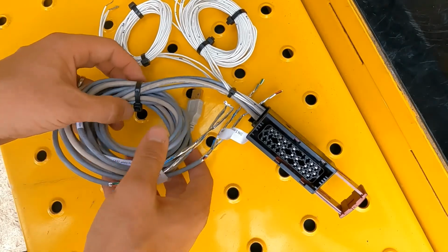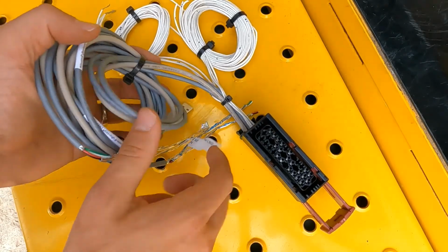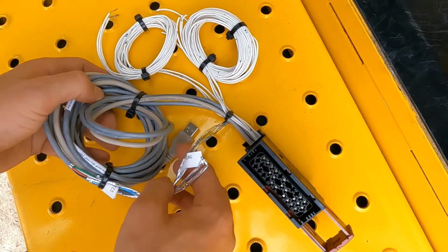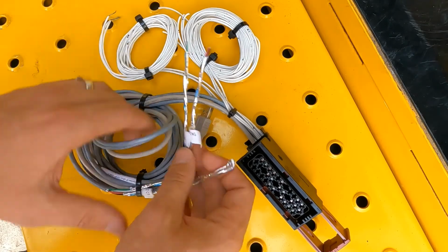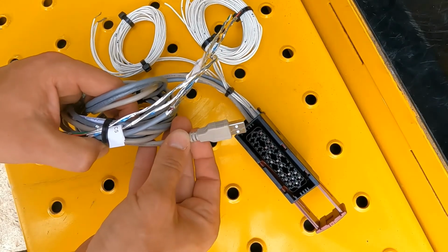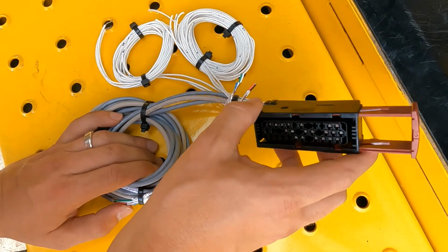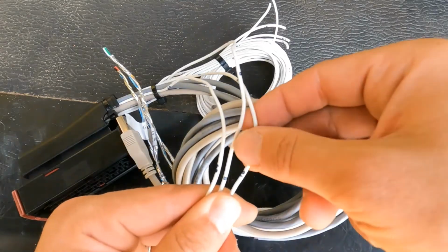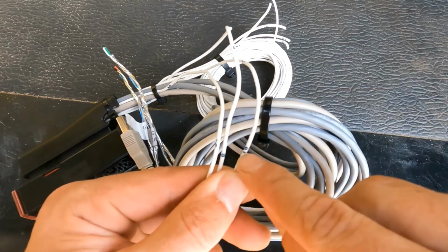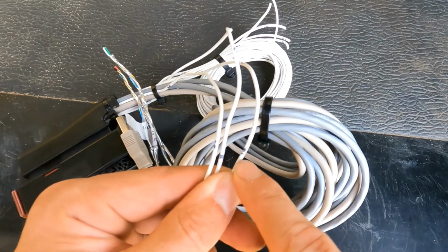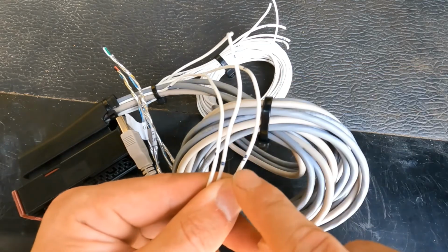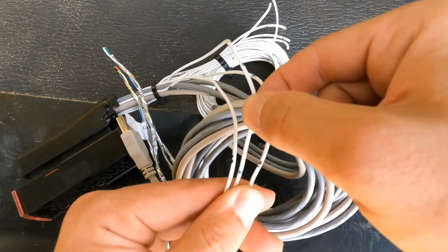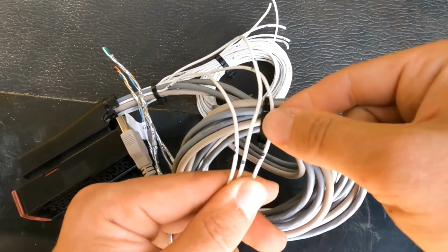The CAN bus wires are going to be the gray wires you see here. The beige will be the USB. We're going to get this ready for the installation as well. As you see here, I even labeled each of the wires as to how I wanted to install them. And here's a USB, and this end goes to the TCG4. The wire harness is actually inkjetted on each of the wires to match the pinout in our catalog. So we're going to want to locate wire 10, wire 8, and wire 9. 8 is power, 9 is ground, and 10 is ignition.